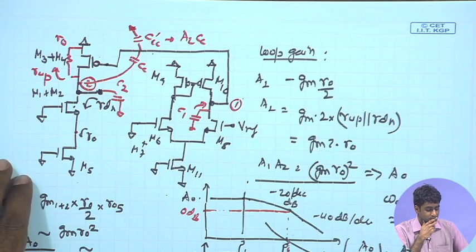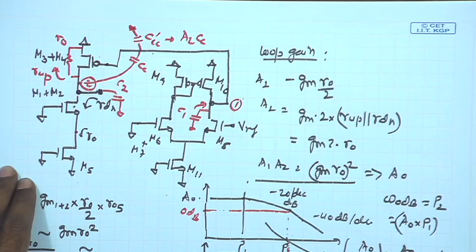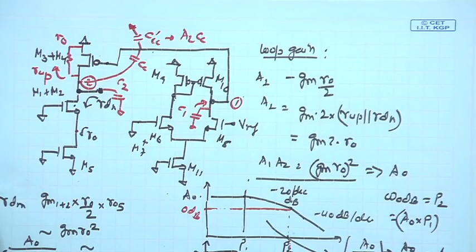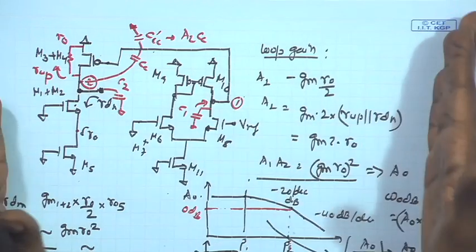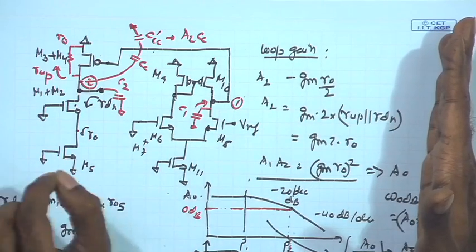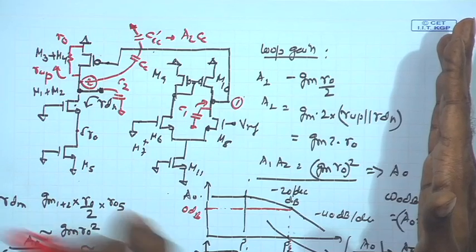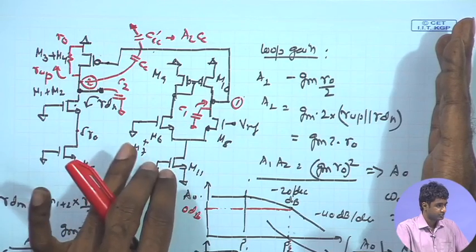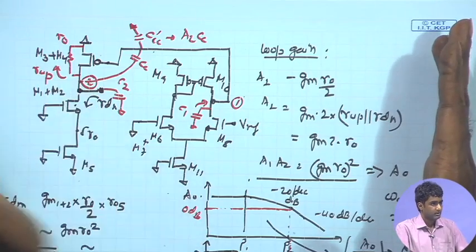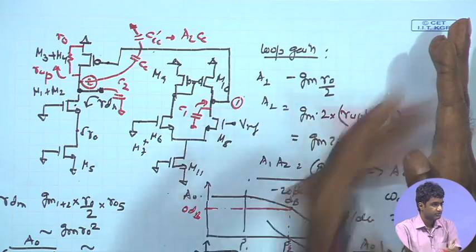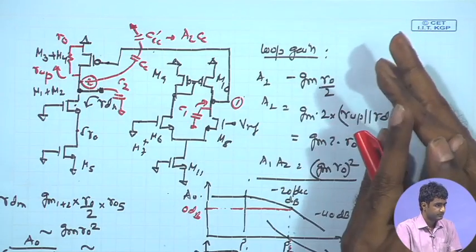For a one stage amplifier we can do this analysis, but if there are multiple stages, then how do we analyze phase margin and other things? Ultimately you have to make one of the poles a dominant pole, which is at a much lower frequency compared to the others. So, even if you have 3 stages, the target will be to choose one of the nodes which can be made the dominant pole. You can push it towards much lower frequency conveniently. That will become our dominant pole, and if there are other poles but they are at sufficiently higher frequency than this one, then it is okay, you can still meet the phase margin.